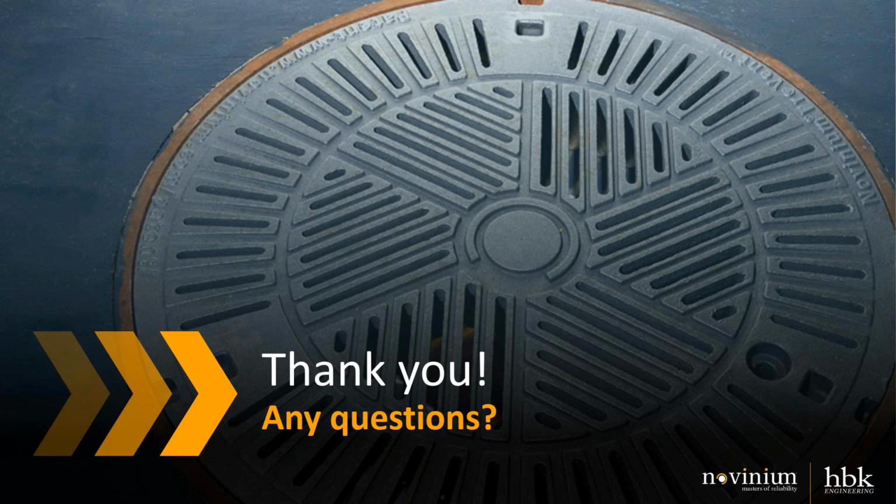But we still would not be able to tell anything about the condition of the cables in between those two duct entrances or the condition of the conduit package itself. Some of the other things that we've been looking at with some of our other utility clients is they've asked us a similar question, and what we've done is we've proposed things like going out and simple rodding and proofing of ducts, and we've gone as far as utilizing smart pigs to pull through the existing ducts to make sure that there are clear paths for proposed and planned cable installation programs for the future.